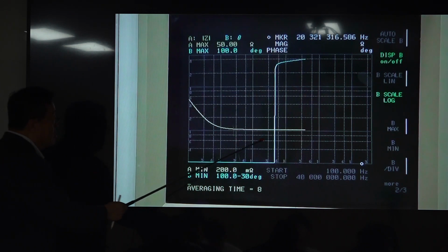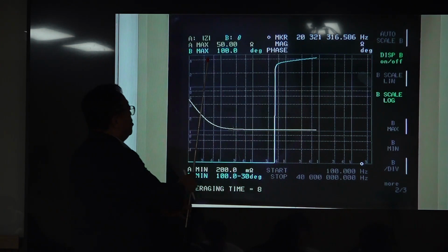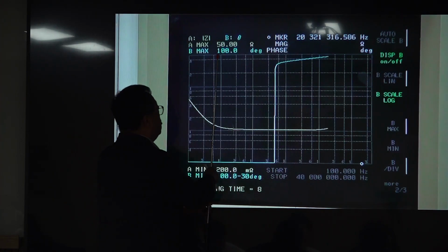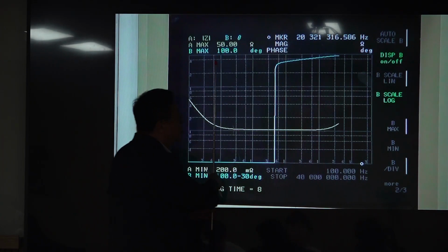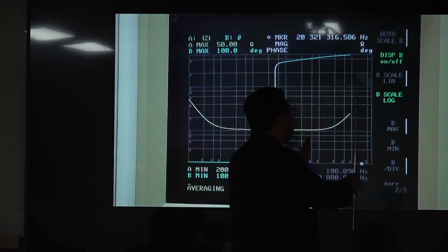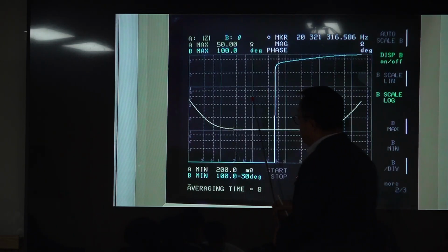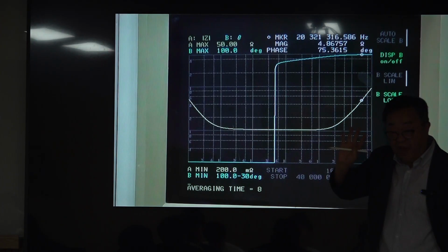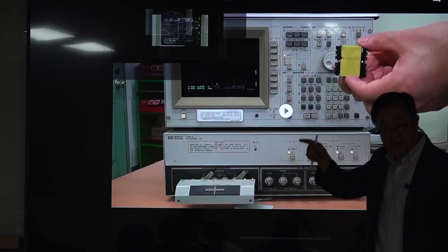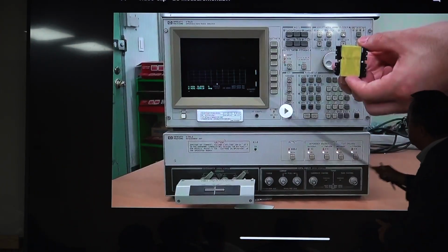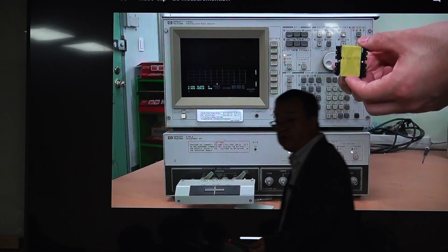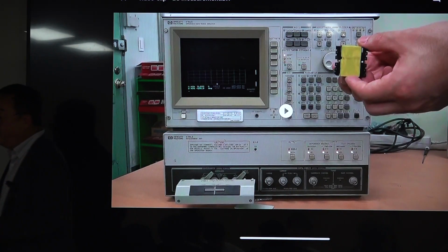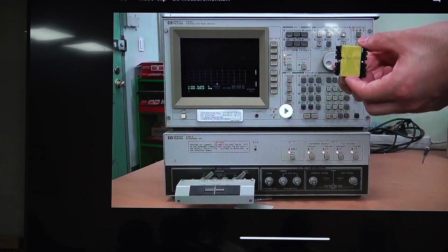So this is a capacitor just until the frequency below this line. After this it is a resistor, and in this frequency range it is an inductor. Okay? So I don't know the frequency here. So you cannot expect that the device will work as a capacitor at high frequency or medium frequency range. Okay? So this information is rather important.